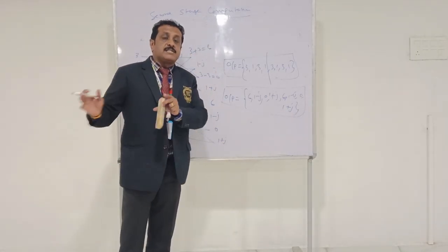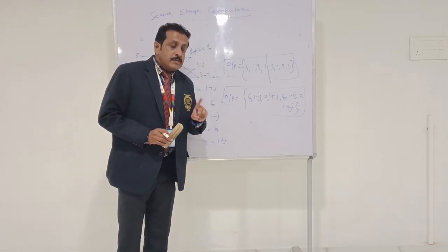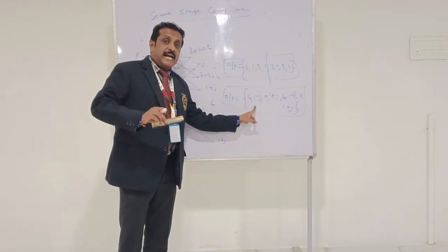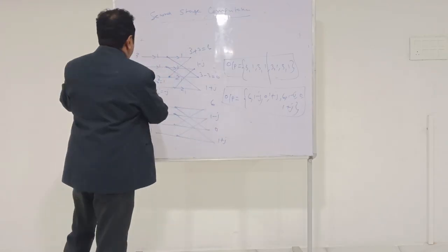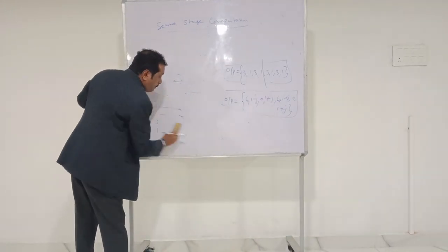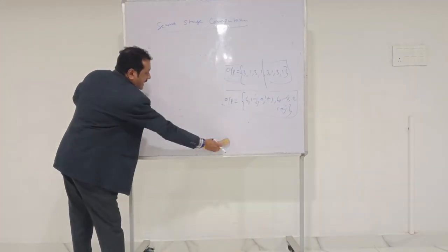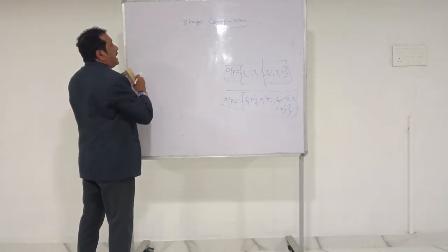Now we come to the last stage, the third stage computation, which is a single 8-point. Whatever the output of the second stage is will be the input of the third stage computation. So we need to draw one 8-point DIT flow graph with the input being the output of the second stage. That is the final stage of the DIT algorithm.